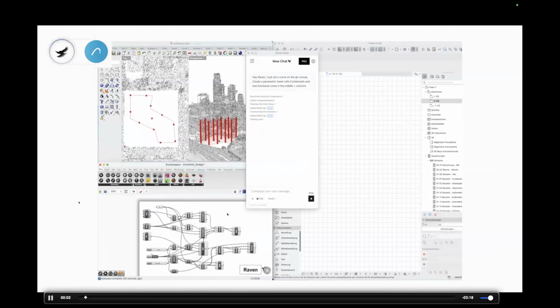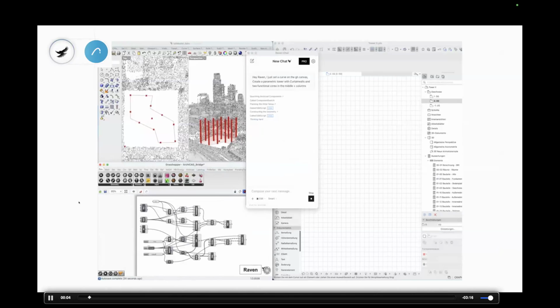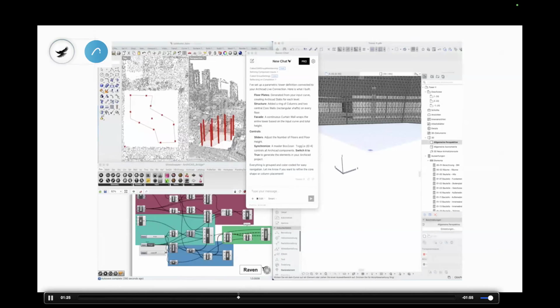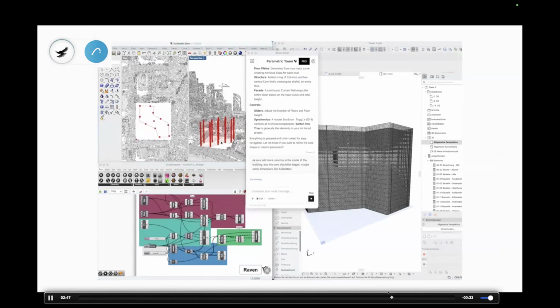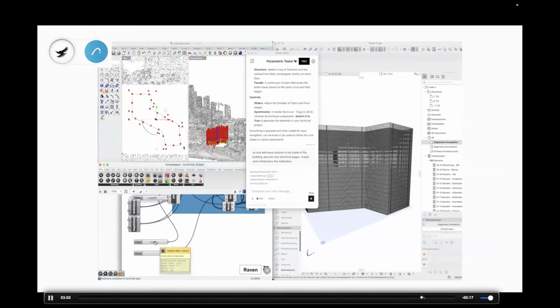And the same is true for ArchiCAD. Depending on where you are located geographically, or even just within one country, it's very split between ArchiCAD and Revit. So the same is true for ArchiCAD in this case. Fairly simple office massing, and then it gets pushed into native ArchiCAD geometry. You can see with the right facade tonalization already applied, it's all like a BIM object from there on out. And you can make changes, and the ArchiCAD bridge will update them in ArchiCAD.